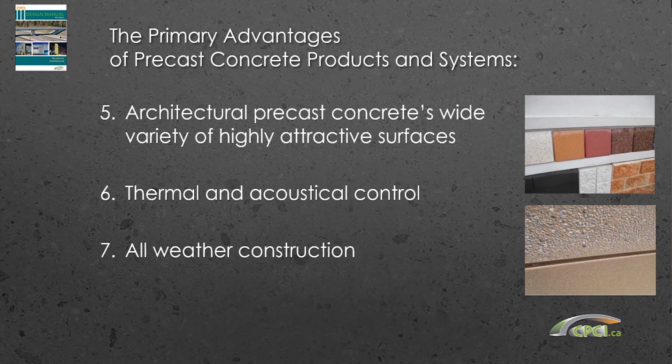Architectural precast concrete is very attractive in a wide variety of finishes, so we can provide different shapes, different colors, and different types of finishes in precast, and also good thermal and acoustical control, and obviously all-weather construction. We don't have to be shut down in a precast plant due to poor weather, and projects can be built on site by trucking and craning pieces and continuing through winter construction without worrying about heating and hoarding on site.